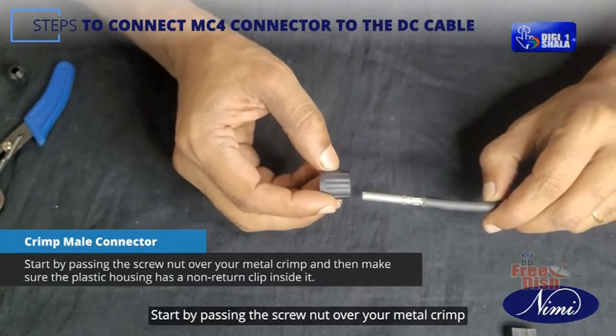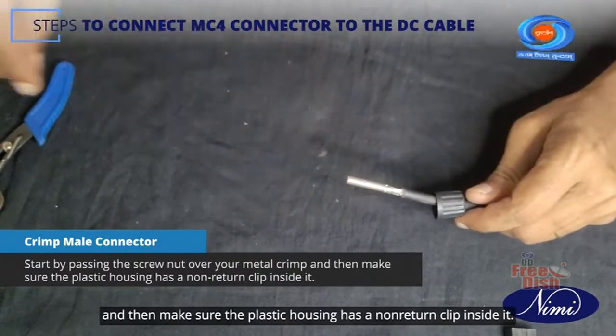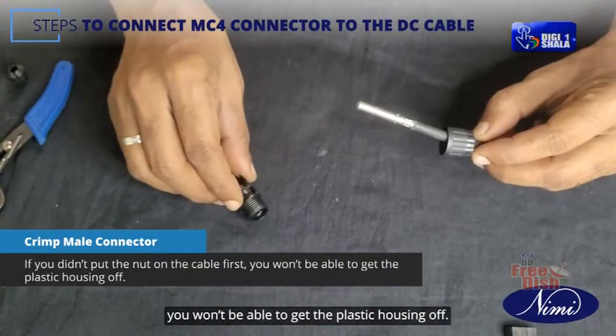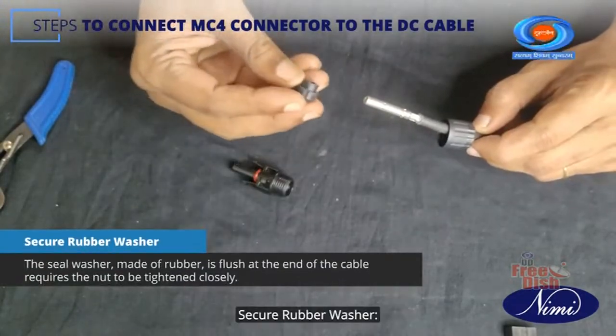Start by passing the screw nut over your metal crimp and then make sure the plastic housing has a non-return clip inside it. If you didn't put the nut on the cable first, you won't be able to get the plastic housing off. Secure rubber washer.